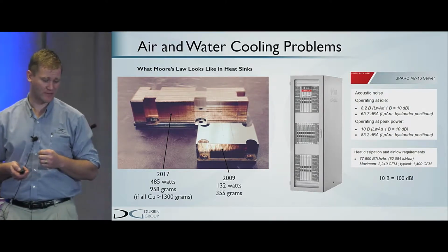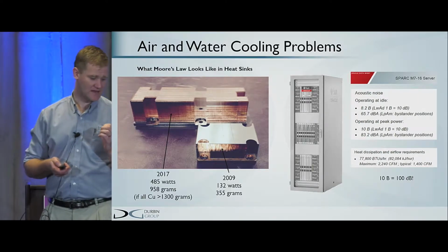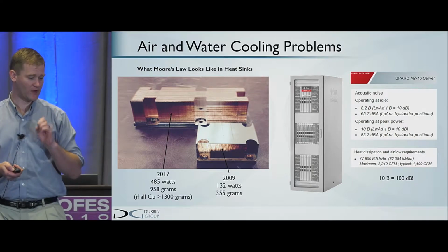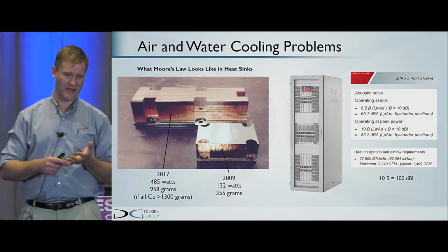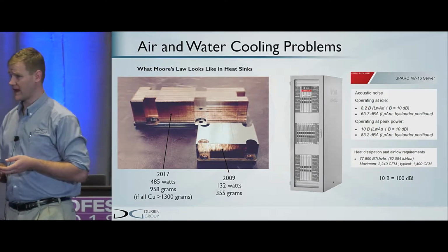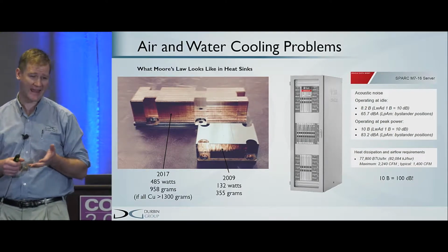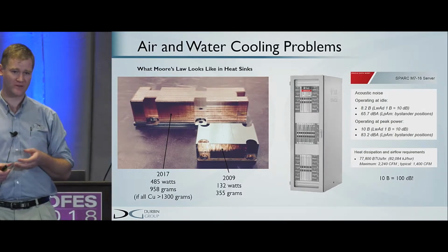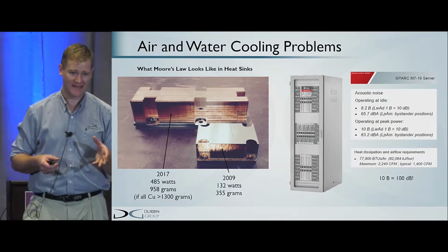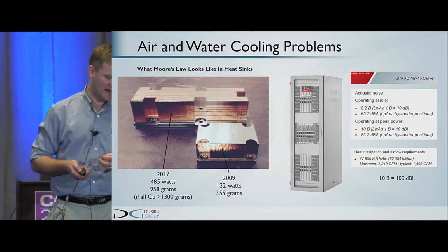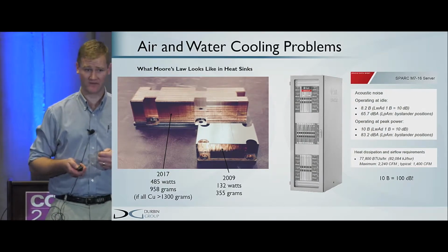And water's not much better. You can get some pretty good volumetric savings by going to cold plates, but it's plumbing intensive. You get a 10 to 20 degrees C rise from the input to the output, and you have toxic corrosion and biocide inhibitors, quarterly testing, galvanic corrosion concerns, and accelerated mean time to failures.